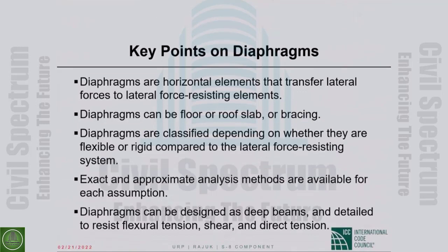Key points on diaphragms. Diaphragms are horizontal elements that transfer lateral forces to lateral force resisting elements. Diaphragms can be floor or roof slab or could be bracing. Diaphragms are classified depending on whether they are flexible or rigid compared to the lateral force resisting system. We have talked about that.